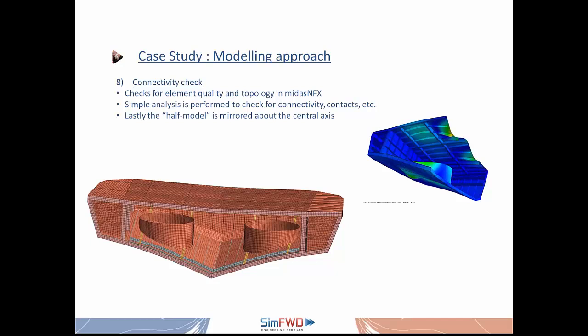Our approach usually is that when we have a model ready to run, we first run a simple model analysis to check for connectivity problems or non-linearity problems, and we then follow with the linear or non-linear static or any other simulation that we would like to run. You see here also that you can directly utilize your mesh to mirror it and have a full structure if it is needed in that case.